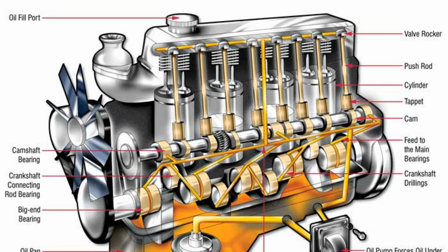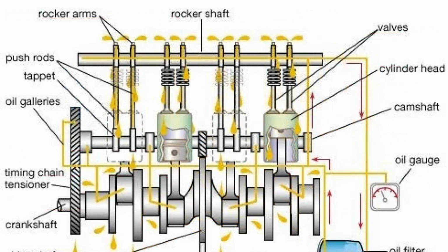Relief and pressure-reducing valves installed in the area of the oil filter or oil pump are responsible for pressure relief in such cases. The signal for their activation is the data continuously received from the oil pressure sensor. If, for example, the oil filter becomes hopelessly clogged, the bypass valve opens an additional channel of fluid flow bypassing the filter to prevent the engine from stalling.